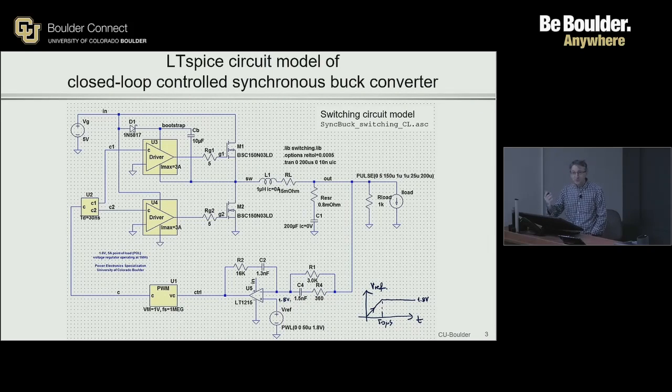Because in reality, switching converters are actually complicated things. And if you immediately apply a 1.8 volt upfront reference and everything is at 0 and you start switching, you would see a large inrush of current at the beginning with the converter trying its best, pushing the duty cycle to the limit in order to try to bring the output voltage to regulation as quickly as possible.